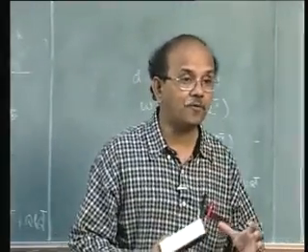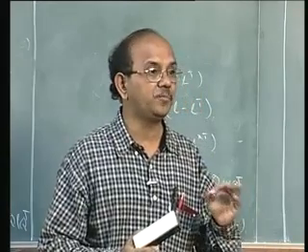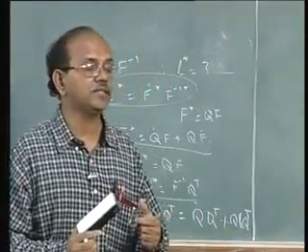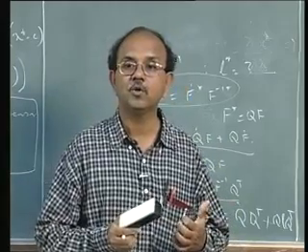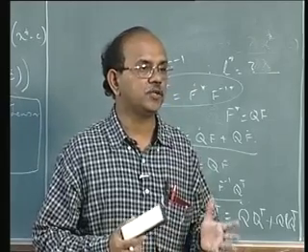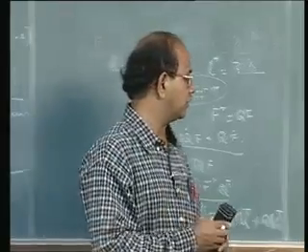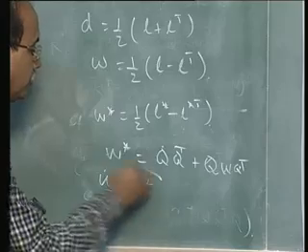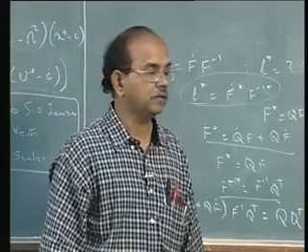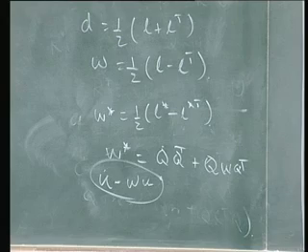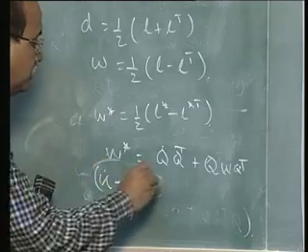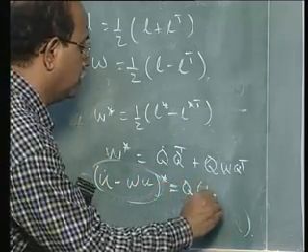One is that we can now have combinations. It is not that every independent quantity has to be looked at whether it is objective or not. It is also possible to have a combination of quantities, and you would be surprised to see that a combination of quantities would be what I would call objective. So let us take a vector, say u. Suppose you take a quantity like u dot minus wu. You will see that this quantity becomes objective. It is not very difficult to show that. In other words, what we mean to say is u dot star minus w star u star is equal to q into u dot minus wu.